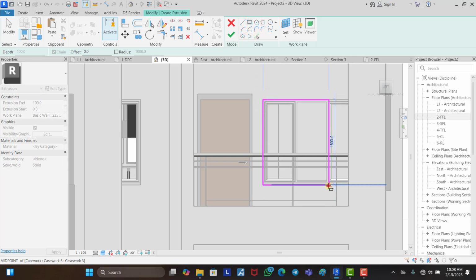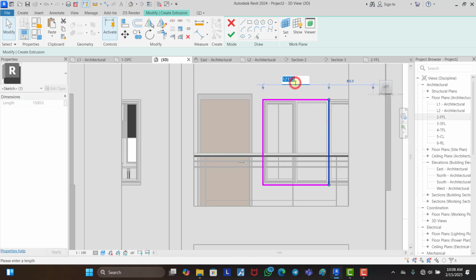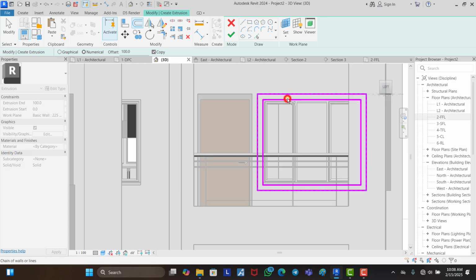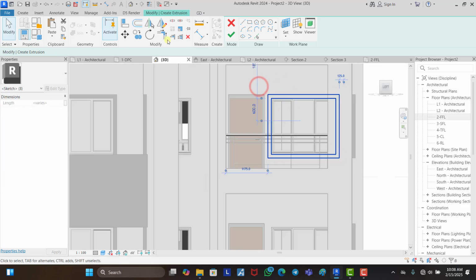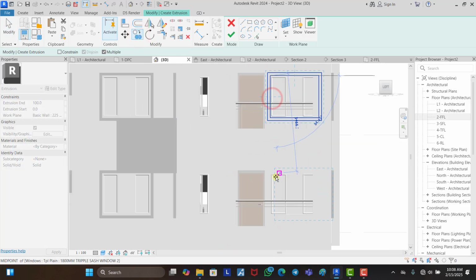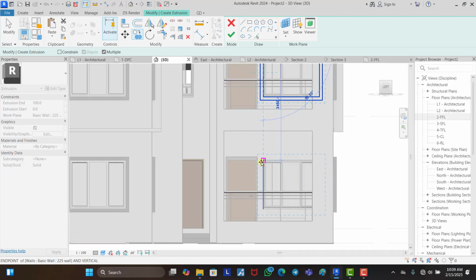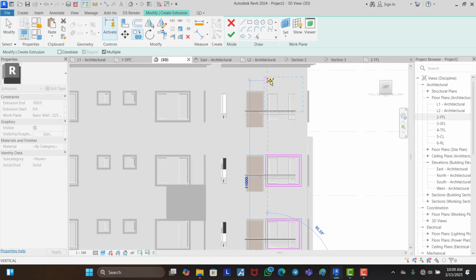Now let's draw this here. We can't see the edge here, but we know the window is 1/8 in width, so you can just come here, click, pick 1/8. Perfect. Then we can take an offset of 100 mm all through. Copy this, select it, and put it down here, and also down here and up here.